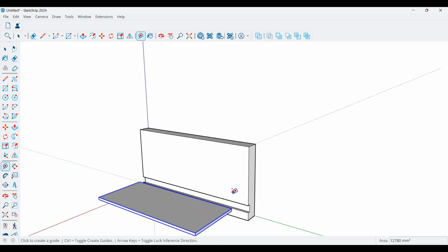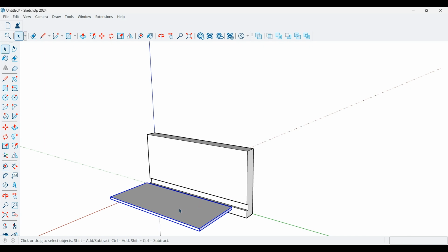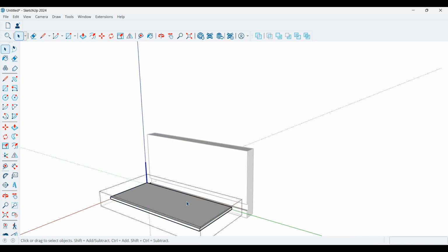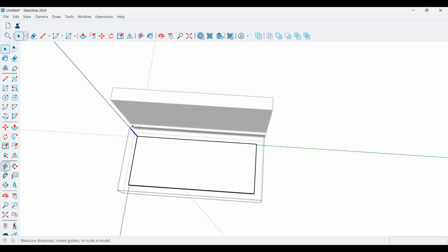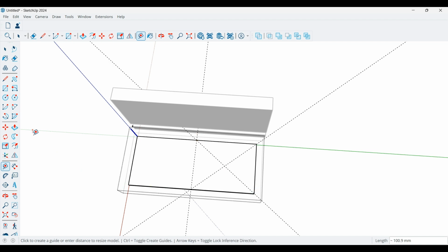Okay. We're now going to double click into the job till we get a bounding box, and that lets us edit it. We get our tape measure tool, and we're just going to come across here and we're going to measure into the middle. So you see a little dot there went up. So the middle is 78. And then we're going to draw the center of this square by putting in diagonals. So from corner to corner, corner to corner. We then get our circle tool and wait for it to hover over the middle.